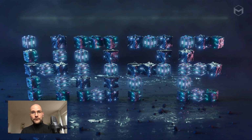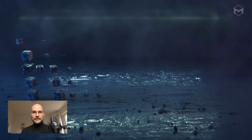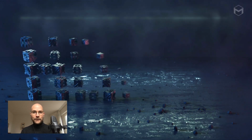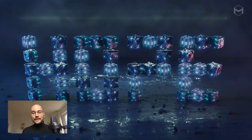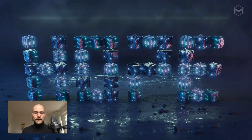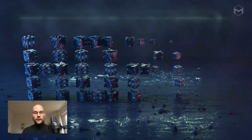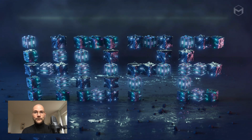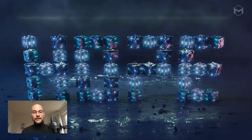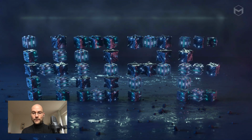Then we're going to create the street material and set up some lighting. And we're also going to create that fog that you can see in the background. And in the end, we are going to set up some AOVs and light groups, so we have maximum control over each of the lights in compositing. And of course we are going to render this out then, and we're going to use the ACES CG color space to render it out.